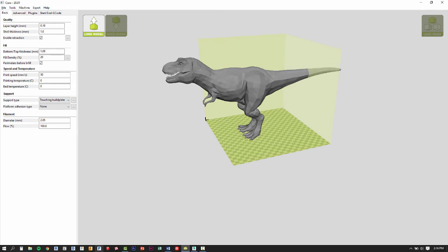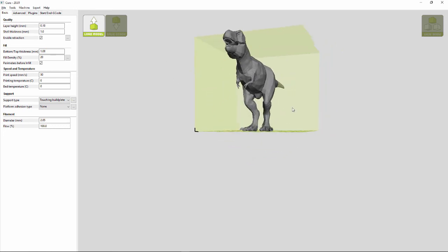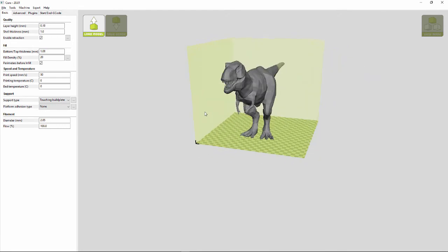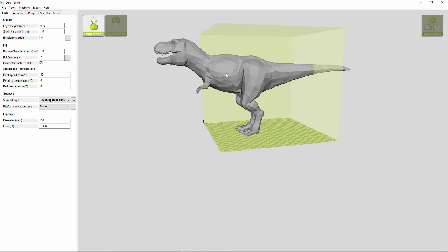And I know that I'm going to open up a web browser here off my screen really quick just to do the conversion. But I know to scale that this T-Rex at 20 feet tall, if I want to print it out at a 1/4 inch scale, should be about 2.5 inches. So I'm going to do a quick conversion factor of inches to millimeters. And if I do 2.5, that's going to give me 63.5 millimeters. That's just a really quick way to begin understanding the scale of my object. If I want this at a 1/4 inch scale, I know my 20 feet is 2.5 inches. That would equate to 63.5 millimeters.